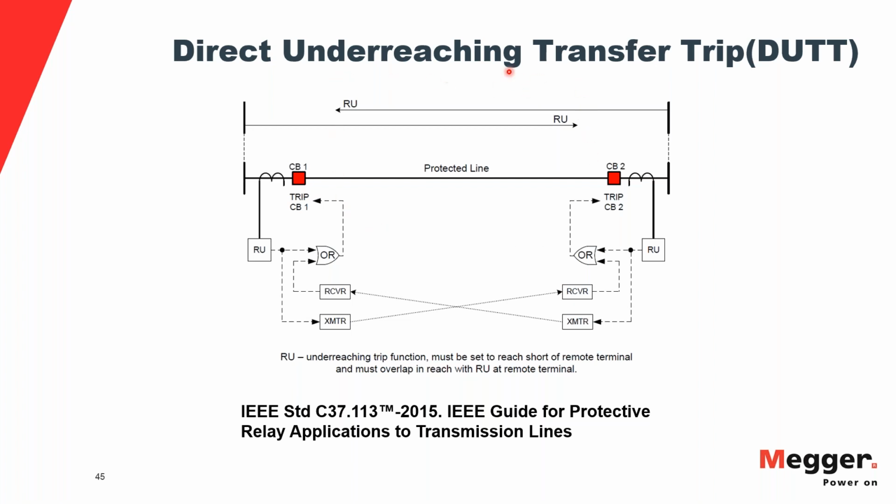And transfer, because this guy is telling the other to do it. So if, let's say, relay 1 sees a fault at this point here, it will trip immediately, and then it will send the trip to this guy over here, and this guy will trip immediately without any other consideration.